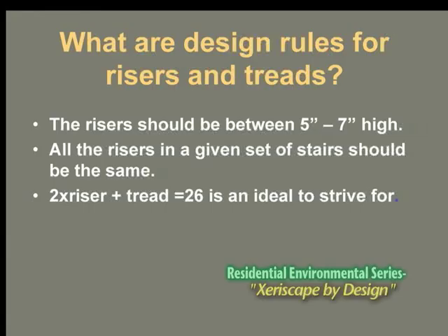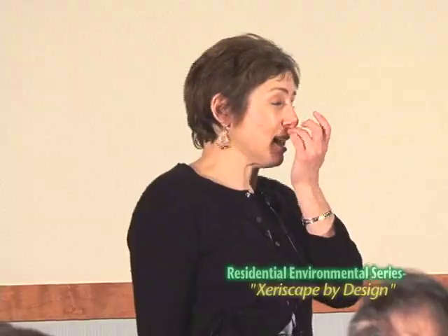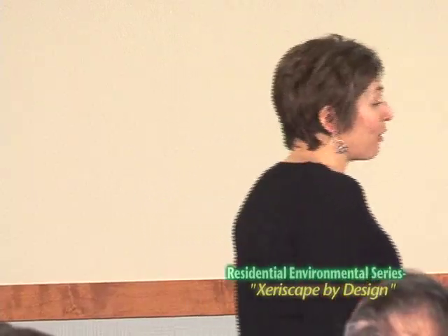Okay, well this is what really had my students glazed over at school today. It was risers and treads, which means steps. There's a lot of rules around this. Like, design's supposed to be creative, right? I think there's rules. I know there's rules. So the risers, the up and down part, between 5 and 7 inches high. Inside, they need to be 6 inches high, and you have inspections on that inside. But in the landscape, we don't have a lot of inspections, but we do have liability. So we want to keep things safe.